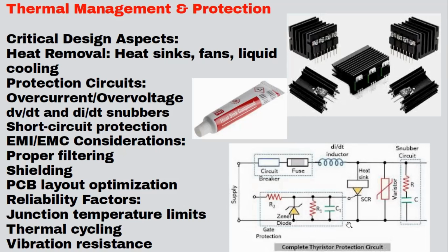You can see here on the right hand side a complete thyristor protection circuit. We have made an EMI circuit, where an inductor, capacitor, and resistor are placed, and it works like an EMI circuit. Then you have reliability factors: junction temperature limit, thermal cycling, and vibration resistance. These are the important parts you have to remember in this particular topic.